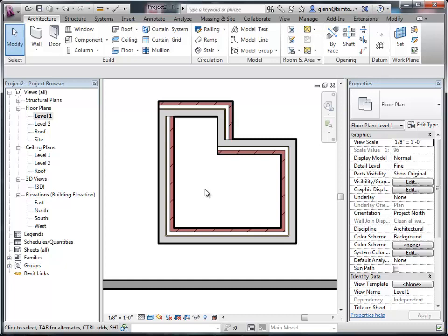For the little practice exercise I'm going to give you, we have some wall types already defined for you that are very common for residential construction in Northern California. Some wood frame walls that have stucco, siding, or shingles on the outside. But we can adapt and adjust these whenever we need to make our own wall type. Let me show you how that works so you know where it came from.